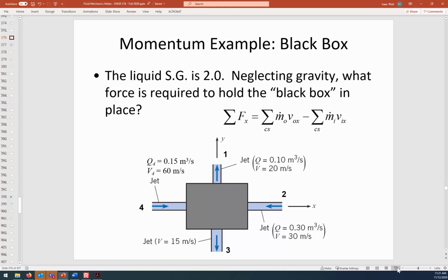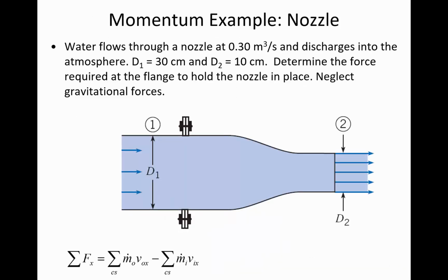This time, though, we need to address the issue of nozzles. And here's what I'm going to tell you about nozzles. In this depiction, there's a jet of water coming out of the nozzle. The little blue arrows and the fact that we don't have the solid black line anymore means that this nozzle terminates at a jet, so the water is spraying out and it's not pressurized. After the water exits the nozzle and it's touching the air, it has a pressure of 0.